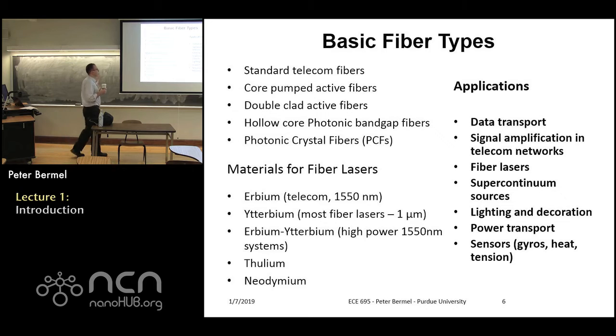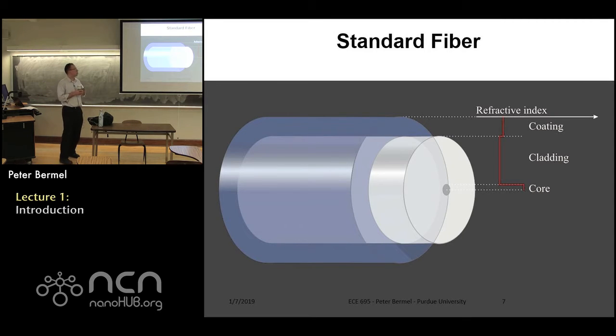And then of course, now there's even interest in using fibers to communicate not just information, but also power. That's an interesting way to communicate power, sometimes called a photonic power converter. It has some advantages, particularly that you don't have to have a physical coupling between two systems, and you can basically sever any electrical connection. So if you're going from, say, high voltage to low voltage, then you can ensure safety is achieved there.